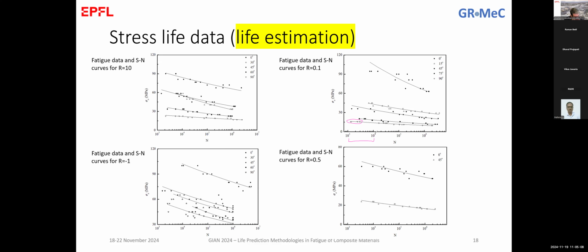And for composites, again, coming back to the previous discussion, this is the difference also between composites fatigue and metals fatigue. In composites, we usually have more scatter for several reasons. Manufacturing defects, misalignment of fibers, and so on. There are a lot of reasons for this. We have more scatter than in metals. And here in composites fatigue, we more or less assume as acceptable results those that are in each stress level.